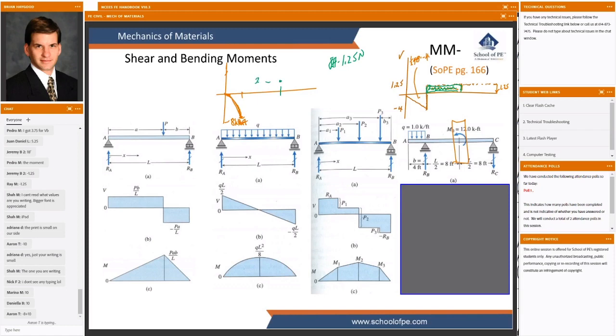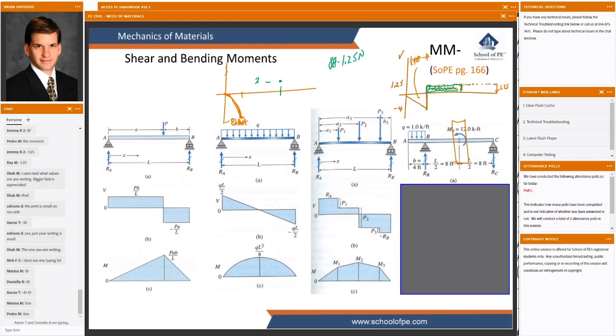And how are we going to get there? Are we going to get there using an angled line or something parabolic, parabolic up, parabolic down? An angled line. Yeah. So our shear diagram suggests a slope on the moment diagram of 1.25 Newton meters per meter. So we start at -8, and then we add 1.25 Newton meters. On the next meter, we add another 1.25 Newton meters, and we keep on doing that until we get to 2 at the 12-foot mark.